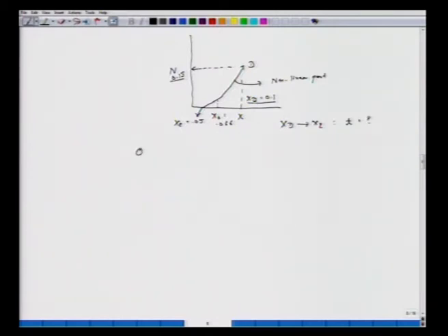We have the general expression for drying, theta equals Ss over A, amount of solids over the area of drying, integral from Xd to X2 of dX over N. This is the general expression for drying, and we are discussing this non-linear part of the curve, from here to here. This extends till X becomes 0.05, at which the rate is 0.